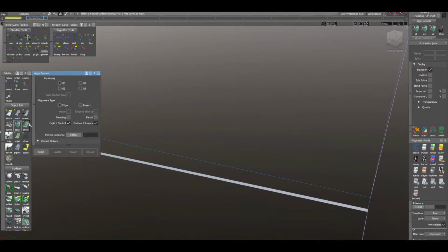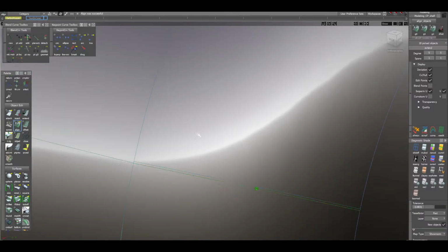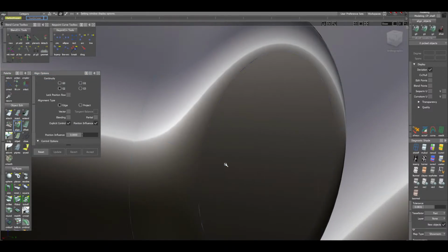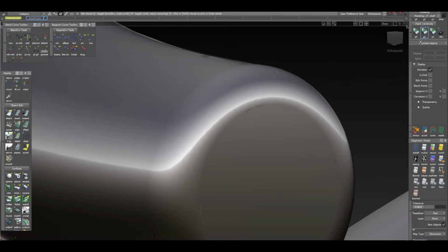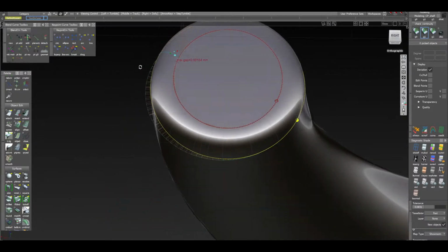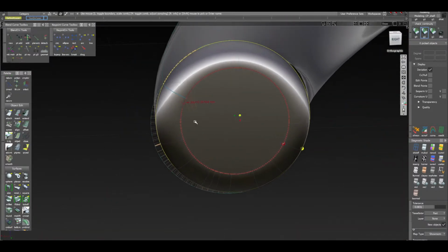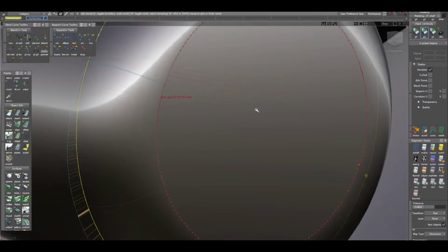Okay. So we can go to the align tool, G2 align, edge align's fine, accept, delete locators. All right, let's check our math. You know, we don't need G2 curvature as long as we're meeting maybe G1, I guess. Toggle the model. Okay, so we're out of position. We're not off by much. You know, for visualization purposes, this fillet's fine. But if you really want it to work to the Class A level, you can go in, manually manipulate the CVs, realign things, whatnot, what have you.